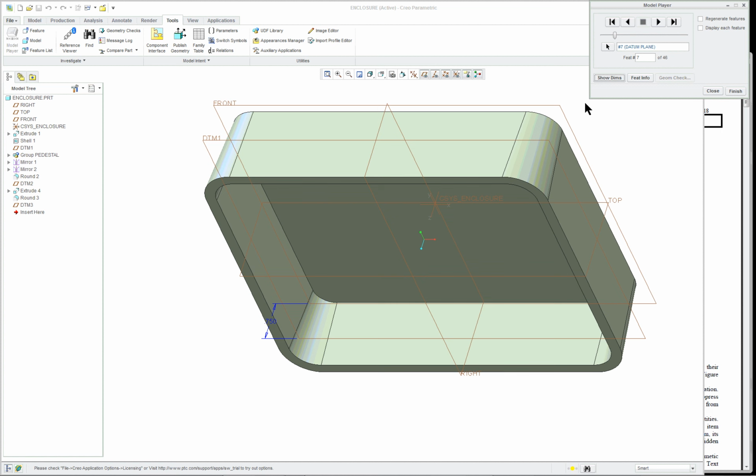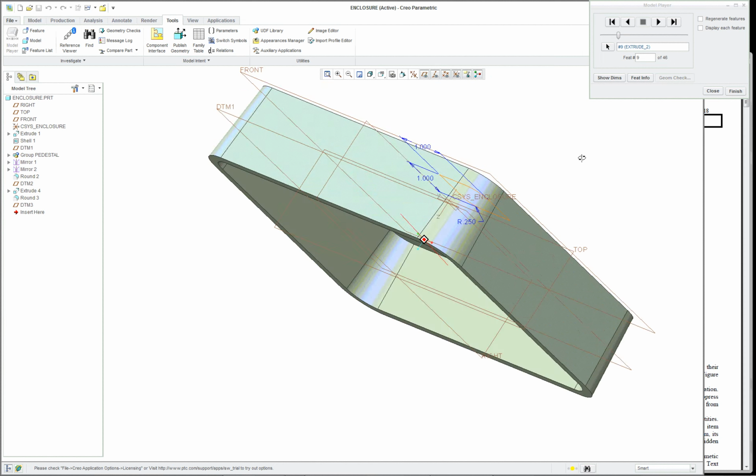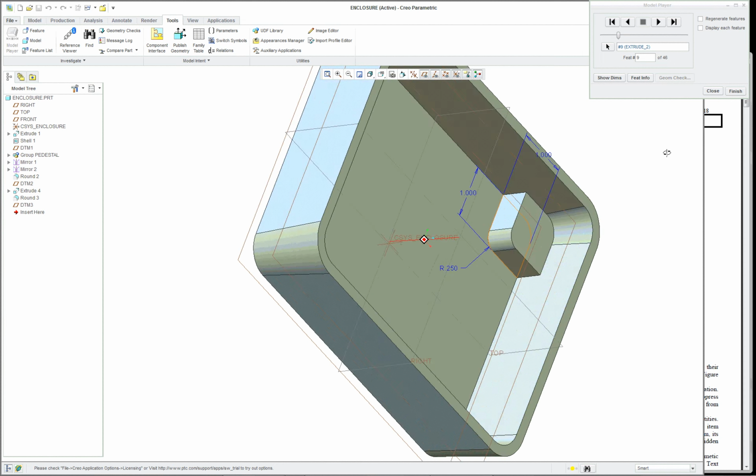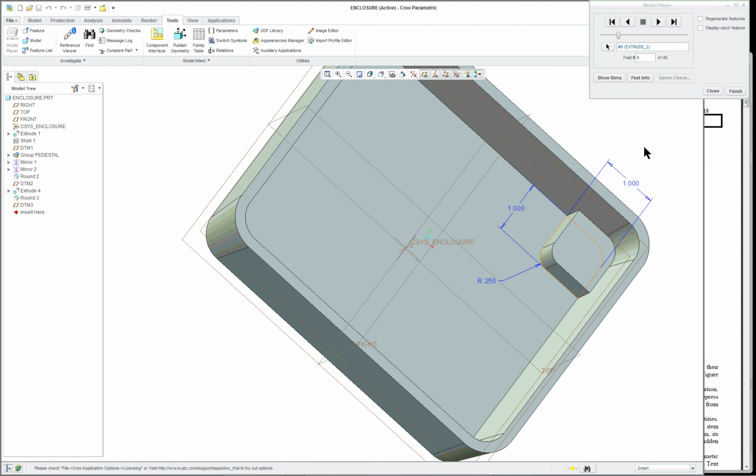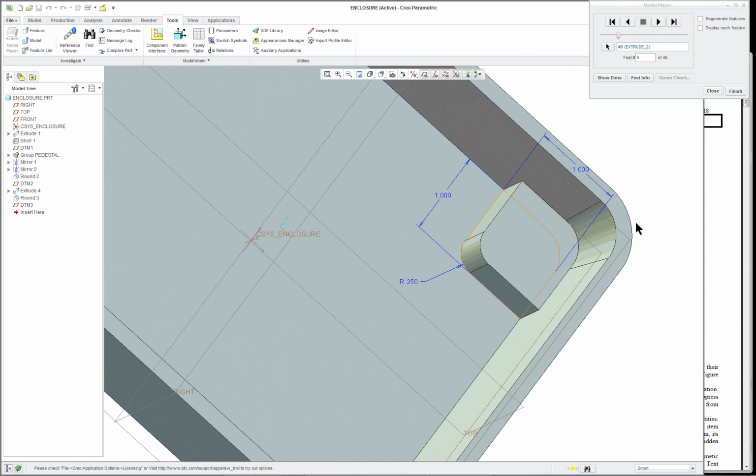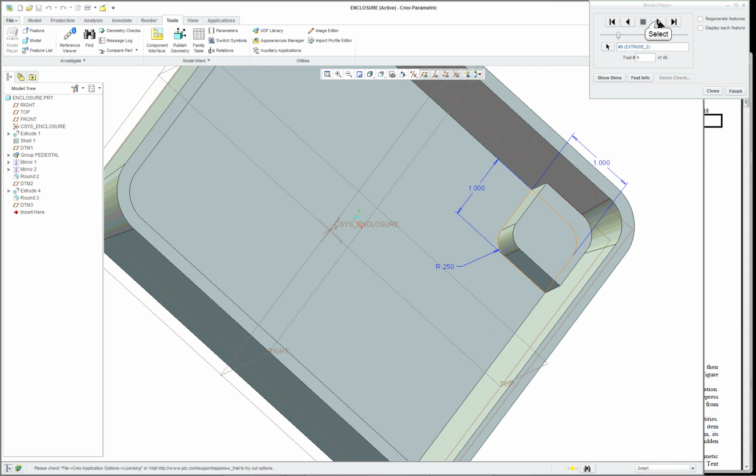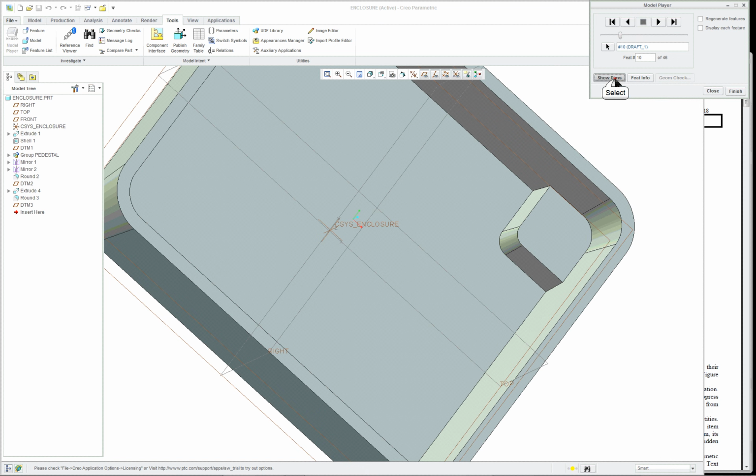Next we're going to offset a datum plane, and do a sketch. The sketch is important here, that we take the correct references. You're going to be using the inside referencing. We have the draft. Each feature has its own draft. And we're going to put this small cylindrical pedestal in here.